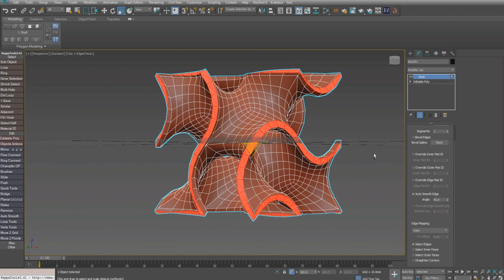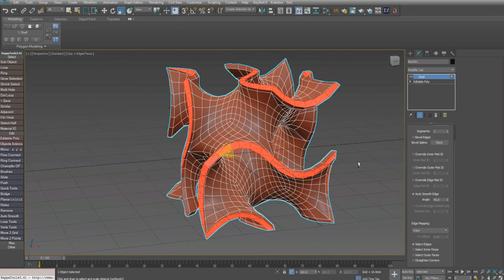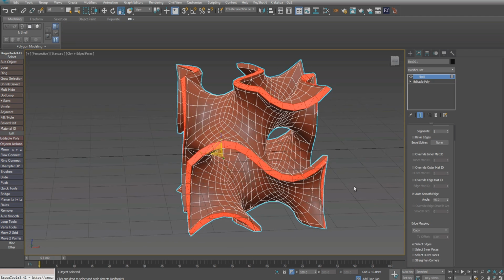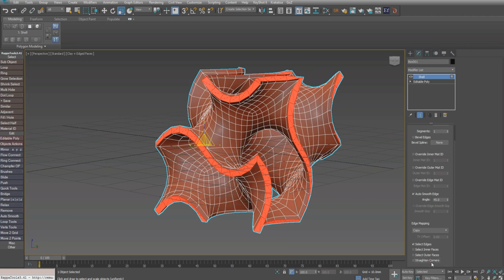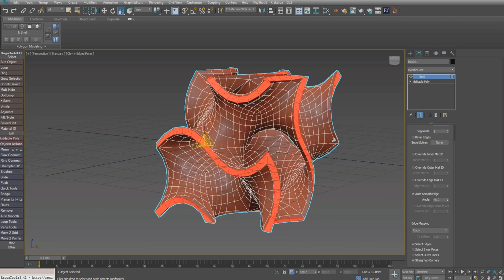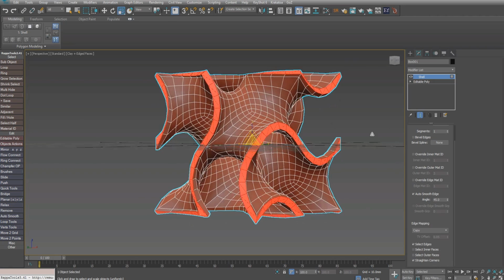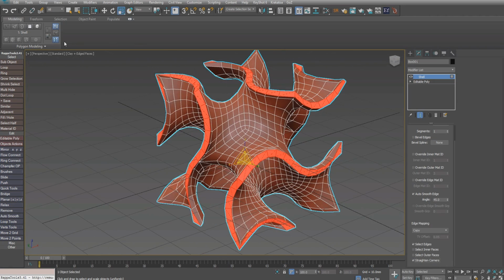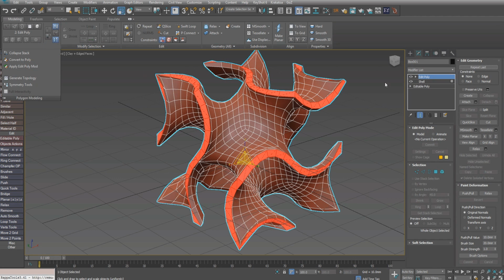And then down here at the bottom, we'll select edges, so check that. And also check straighten corners. That part's optional, but you can see that it does give a little bit better result on the corner edges. All right, it straightens them nicely. And if we're just going to use the object as is, then that'll give us a finer result.